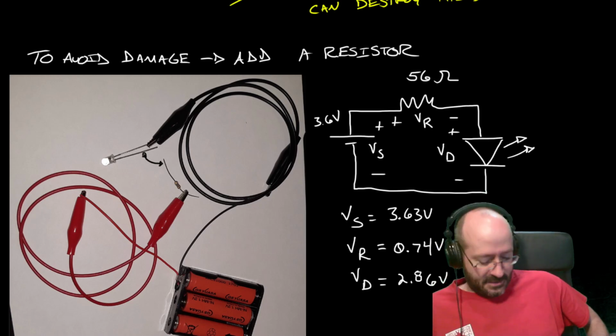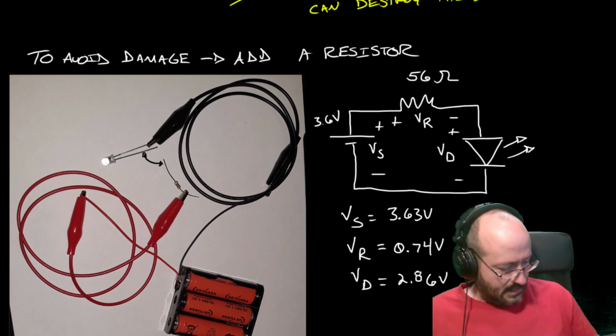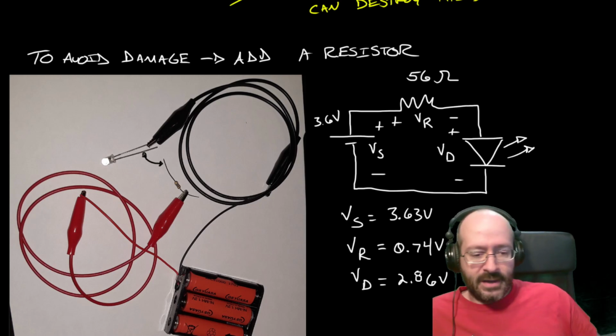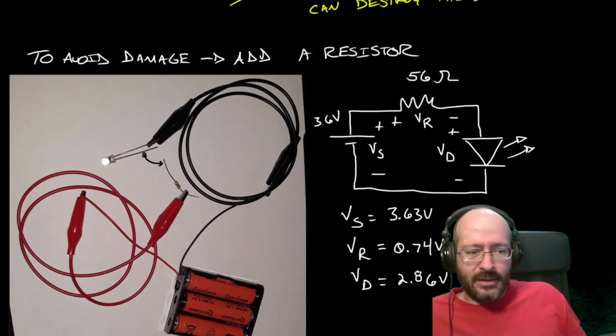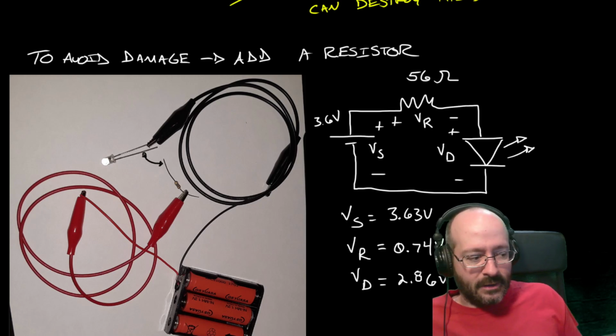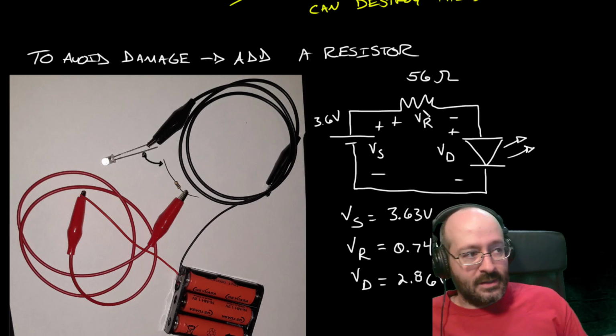I usually have to teach undergrads this. You're going to come in knowing it. You have to figure out how big the resistor should be. And the diode is going to have a voltage that it prefers to settle at. It's called the forward bias voltage, and everything else comes out of that. With these three numbers in this circuit, we have a loop, just like we did when we were looking at